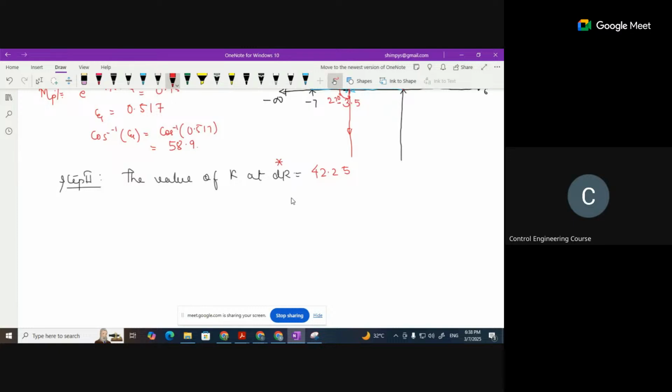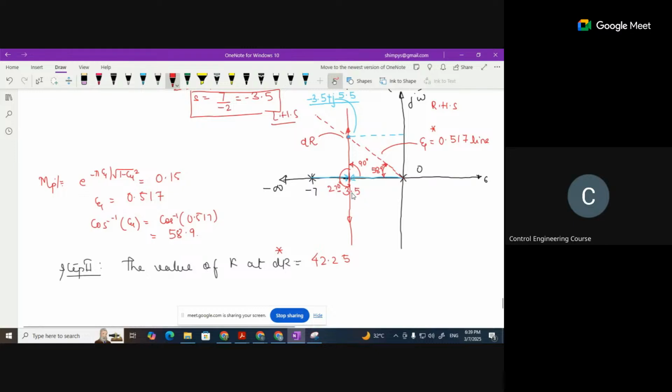when we talk of the compensation in control systems, your dominant poles have the most significant influence on the transient response of the system. When we talk of a higher order system, say third order or higher, there are multiple poles, but only a few poles, those which are complex conjugate, not the simple poles, are basically responsible for the behavior of the system, and these are referred to as your dominant poles.